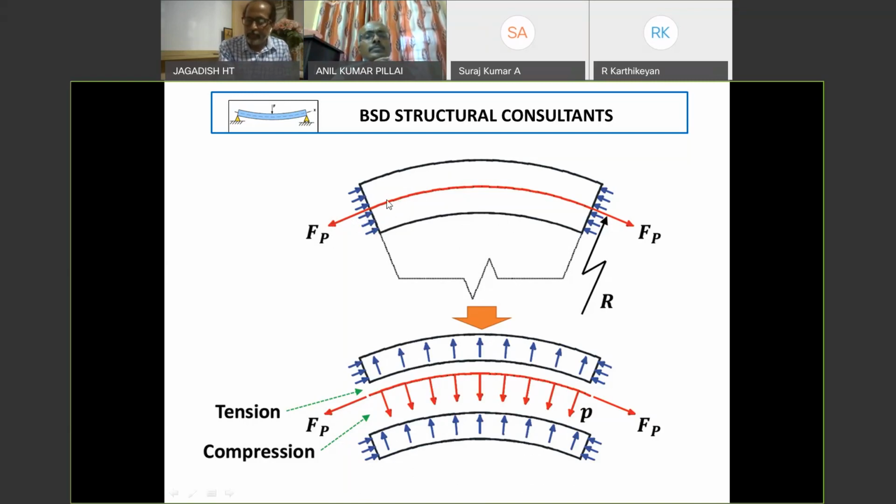If the cable were horizontal, simply horizontal like in any of our flat slabs, it's simple, we just pull the cable and compression happens in the concrete. There is no eccentricity of the cable in that slab. Whereas in a curved dome like this, the cable has got eccentricity, in the sense the force is eccentric to the center of the dome here. So when this force is happening in a curved cable, there will be a pulling force, as the cable tries to straighten out. From here to here, the cable may try to become straight.